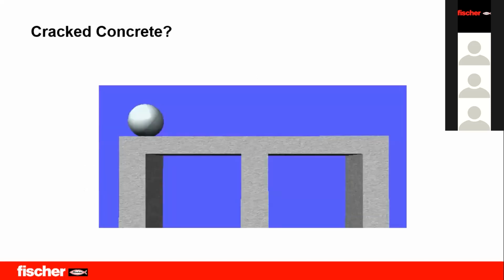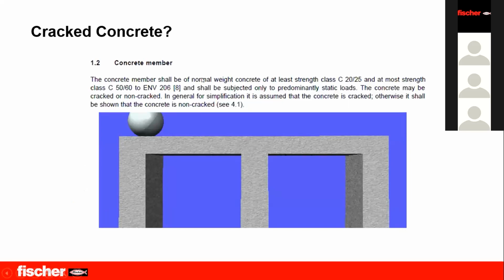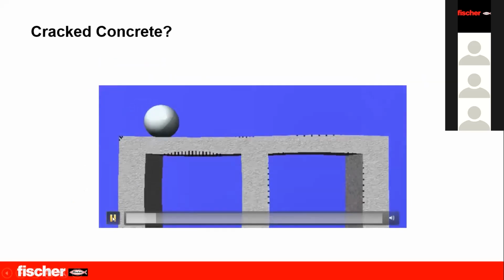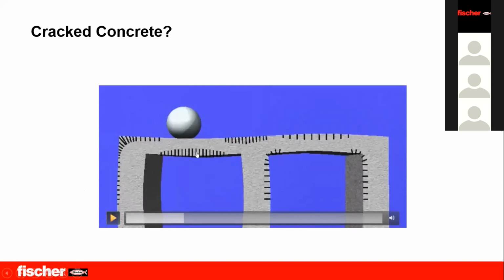As you know, concrete as a material is very weak in tension and very strong in compression. This is the reason why the structural engineer puts reinforcement in the tension zone. If you see here, when the live load comes to the structure, this black line shows the tension zone. In this tension zone, the concrete will crack. A crack with some width will appear in the concrete.